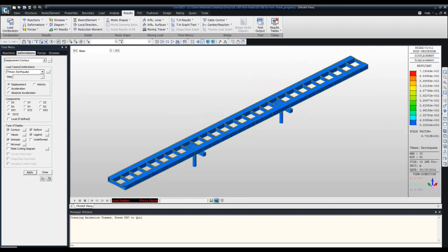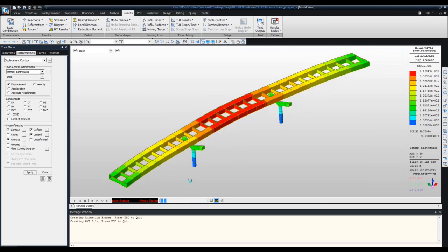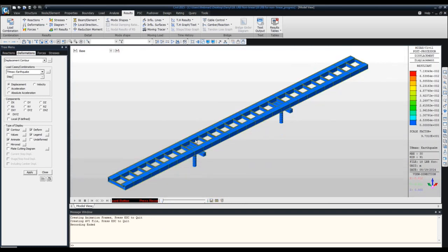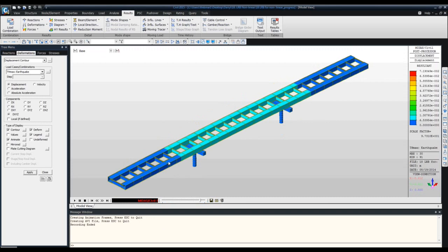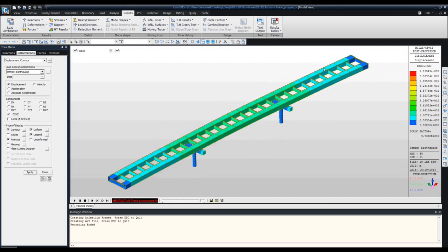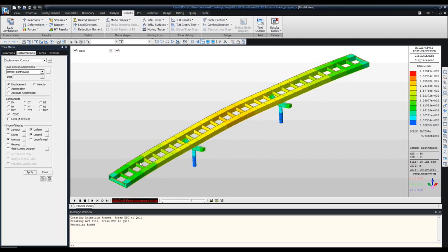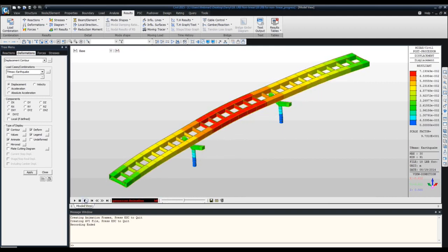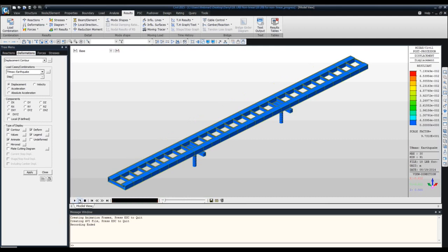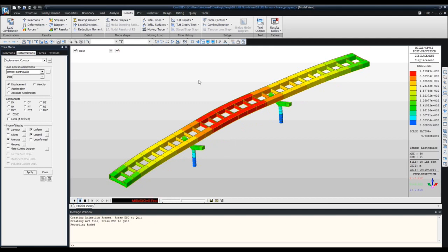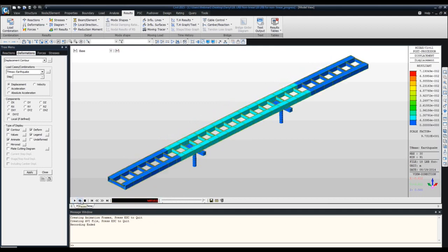So it looks like a little tape deck. Click on that, and as you can see, what happens is the program will actually give you this animation of how the stresses or the deformation changes over the length of the earthquake. So naturally, because I clicked on TH max, the default setting is just the maximum displacement. But you can also see the other displacements that lead up to that critical condition if you use this option.